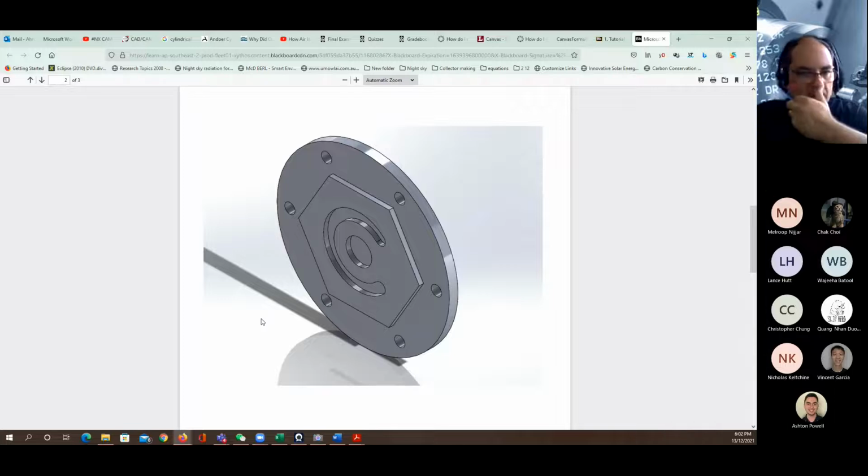Of course, you can have it in the middle here as well, but it doesn't matter as long as we can set that center to be in the middle. As long as you are going to have a circular shape, which is going to have symmetry, we can have it in the middle. Now, the same thing actually can be done with any other cut, because we said that we don't have a specific location for the datum point. The only reason for having the datum point in the lower left corner is that this will be somewhere to be located on the vise holding the part.